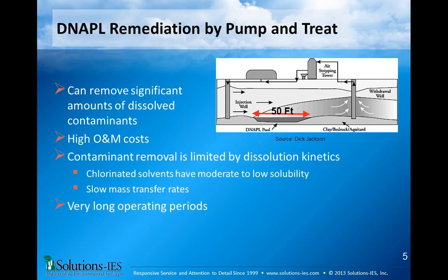But you can put emulsified oil in the high K zones, and as the contaminants diffuse out of the low K zones into the high, they get treated. So for low to moderate concentrations, at least I personally feel we're okay. We're pretty good at treating source areas with that.